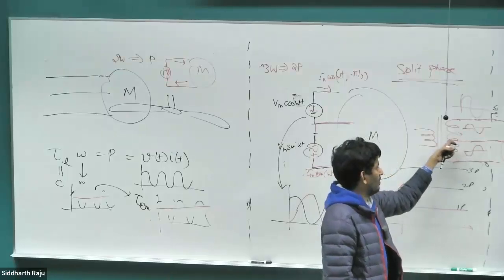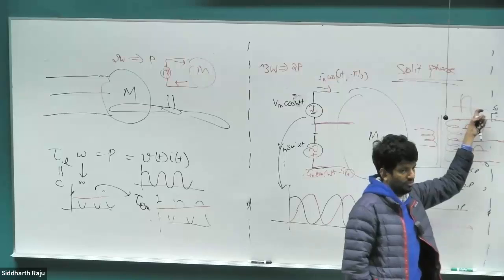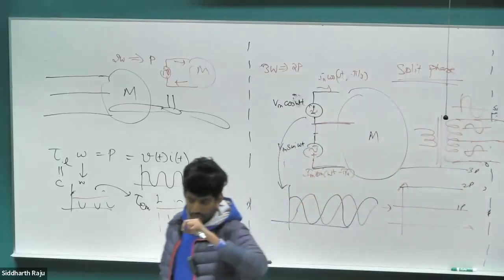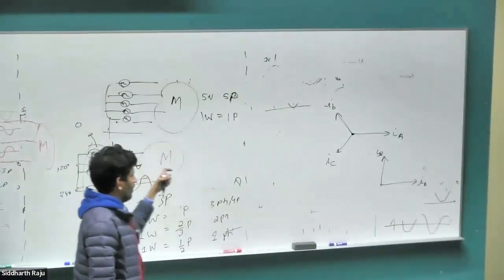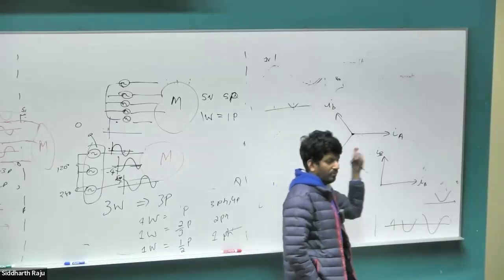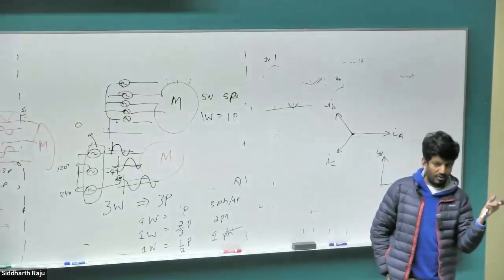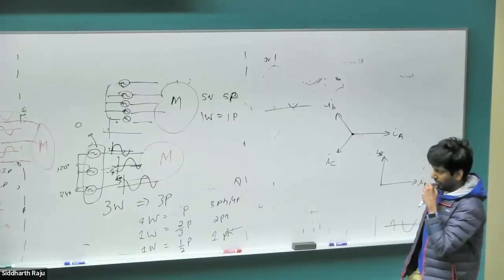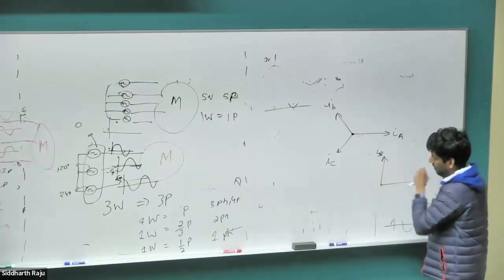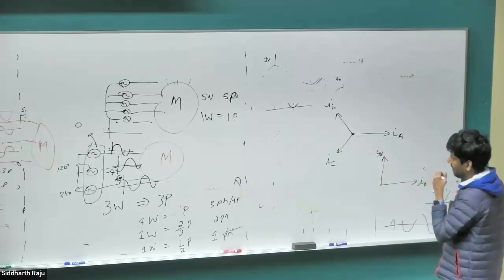In effect, this behaves as just a one-phase system with a net higher voltage. And we will see when we look at motors why we do put it at 90-degree and not 180-degree. Because if you put it at 180-degree, the motor won't even start to rotate because it effectively behaves like a one-phase motor at that point. When you put it at 90-degree, you can create rotating space vectors which will start rotating the motor. So a two-phase system is actually separated by 90-degree, not 180-degree.